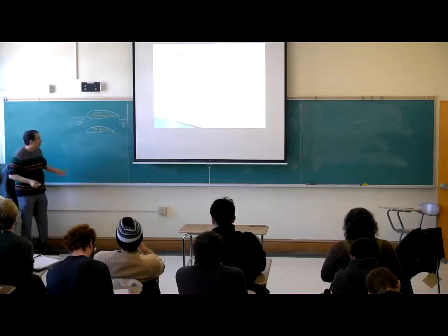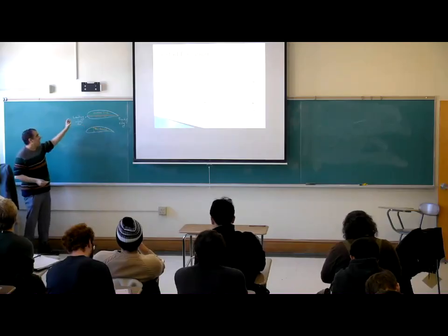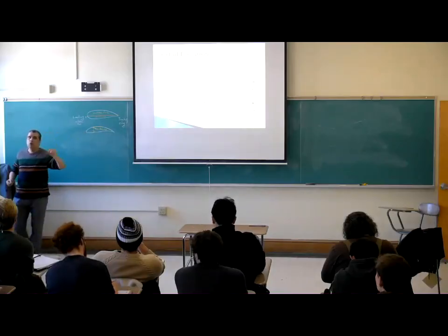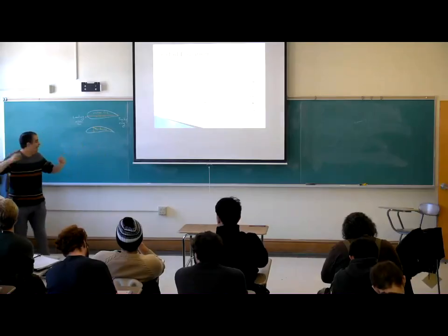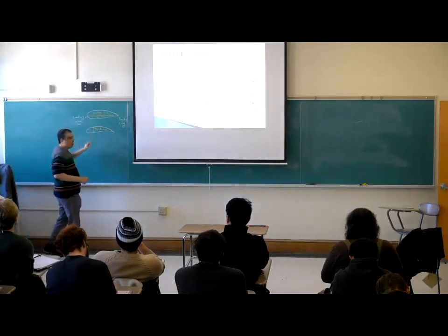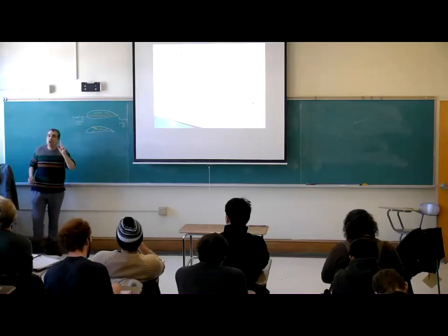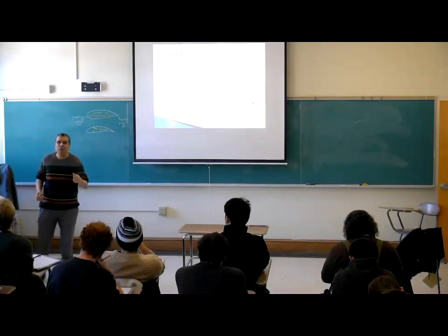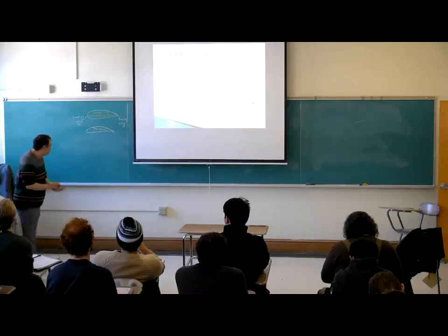of the airfoil. So airfoil has three main characteristics: camber line, which is the mean line; chord line, which is a horizontal line connecting the leading edge to trailing edge; and thickness. Thickness is the thickness of the airfoil. I want to tell you how the airfoil configuration came to the mind of the aerospace researchers.